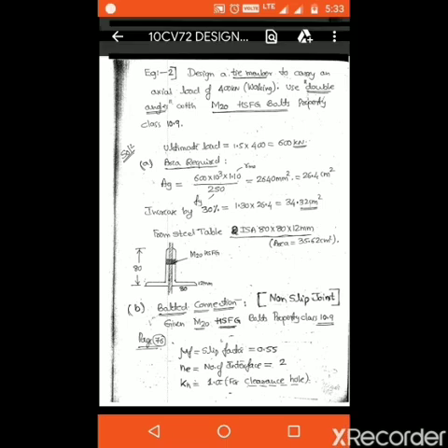For bolted connections with a double angle section, it is a no slip joint. There is no slip between the members or connection, so that is why you have to write no slip connection. Now the given property class is M20 HSFG, with property class 10.9. If you are going to calculate the strength of the bolt, on page number 76 all the equations are given in IS 800 2007. First note down the slip factor, mu equal to 0.55.